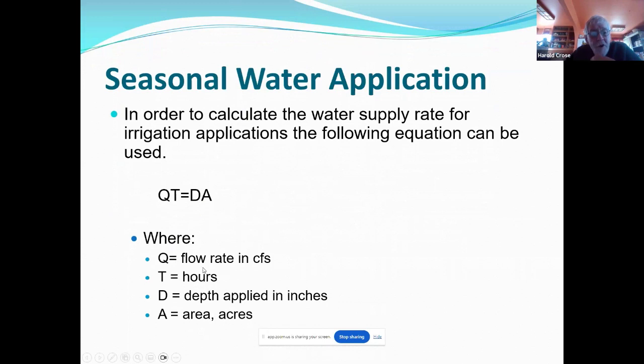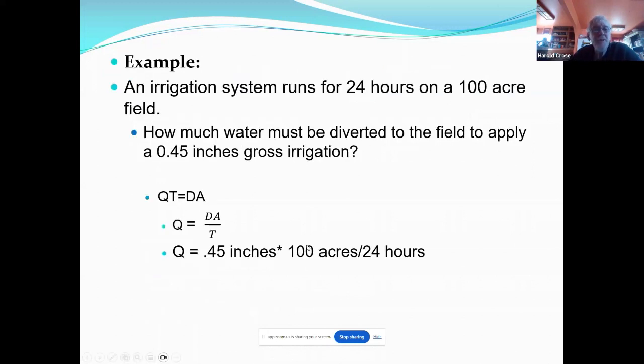That's a good starting point, because if a grower comes in and says, I've got water rights from this stream for half a foot of water, or about 250 gallons a minute, and I want to irrigate 200 acres, a red flag better go up, because they're not going to have enough water unless they're just using it for supplemental purposes. If they need a full season of irrigation, they're going to be irrigating about half that acreage. You can use this formula to determine that.